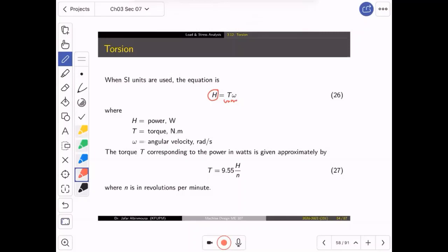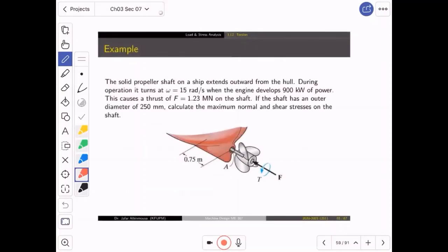It doesn't speed up much, but it will give you good torque that will allow the car to be driven over the sand dunes. But the most important thing not to forget, this is not the trick. I mean, don't just go now and put it in first gear and drive; you have to lower the tire pressure a little, don't forget. Now, this is pretty much everything I can tell you about torque.